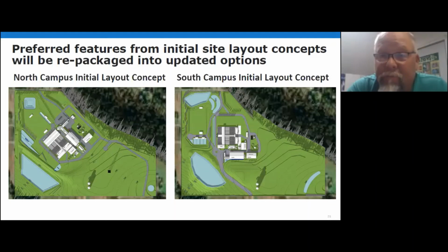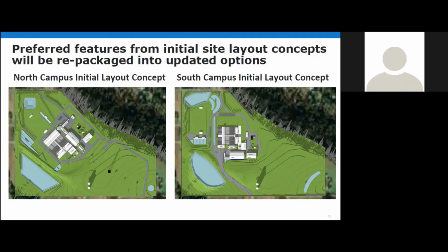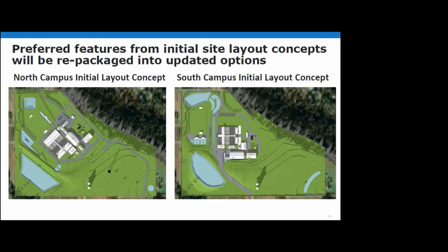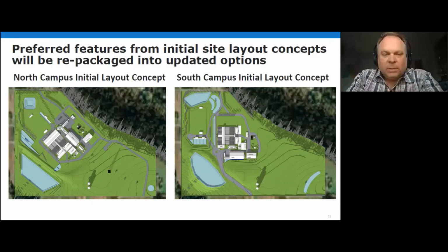It sure is. Maybe I can make a couple comments there. Sure. Especially with the North Campus, what we attempted to do is take advantage of that draw, because our process is a gravity process. The water flows downhill naturally. So we have the processes at the head of the treatment system, the highest point where the water starts, and then it flows downhill by gravity to the lowest point.